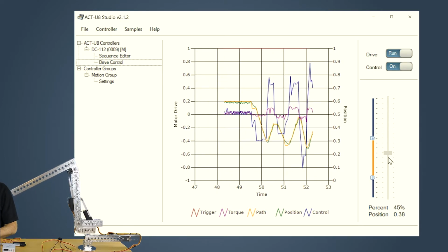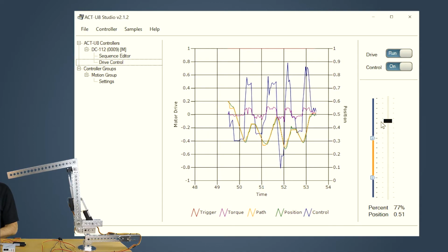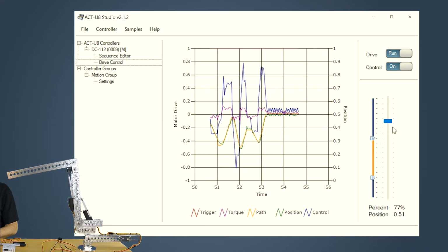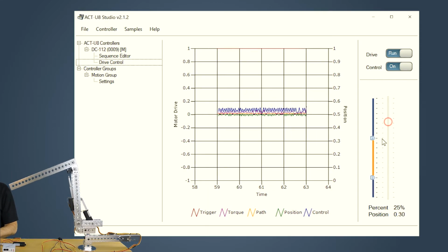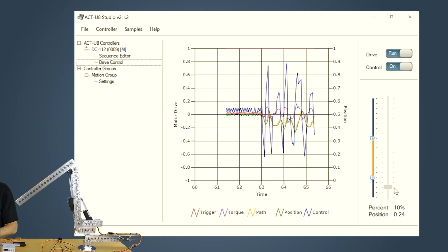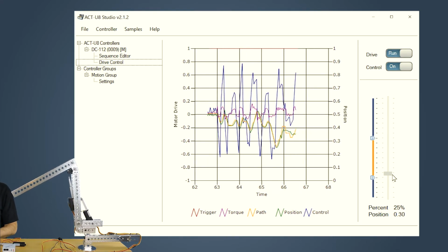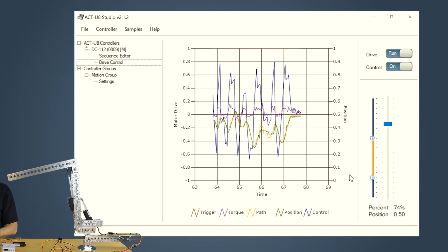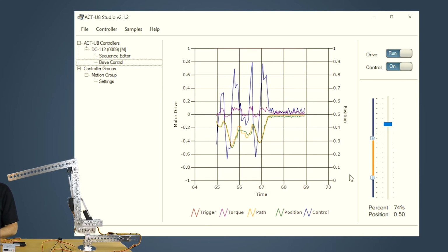So when I move this slider around, the command point of this slider is not going directly to the PID. It's going to a trajectory computer, essentially building a path of trajectories to say, what is the smoothest way to get me from my current position and velocity to the desired position and velocity? And it could include a sequence of trajectories that might include stopping, reversing direction, speeding up or slowing down to try and match. And so you can see if I move it around quickly, it's not going to jerk around. It's going to come up with the fastest way it can respond. And again, the trajectory path that it develops is designed not to exceed the maximum velocity or acceleration that you've set for that linear actuator.